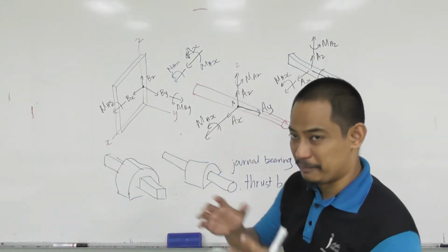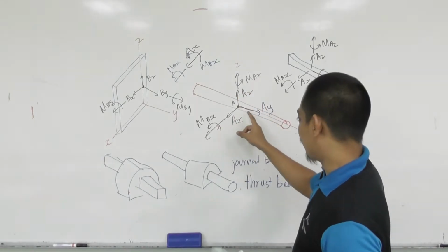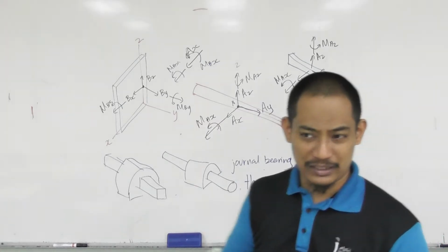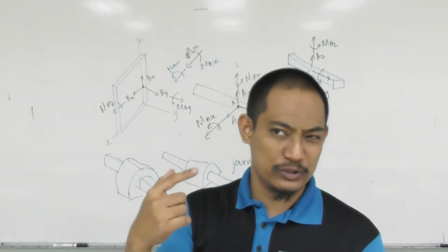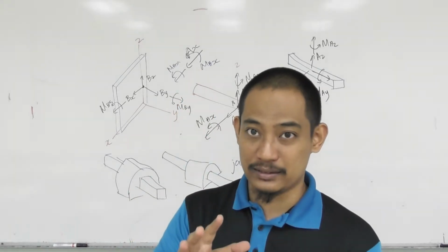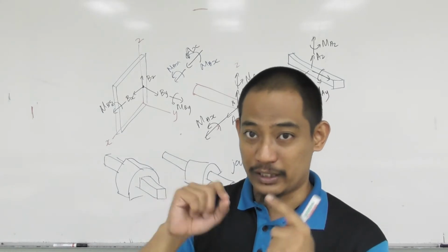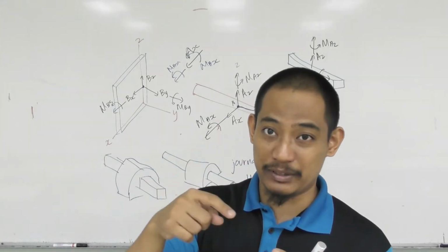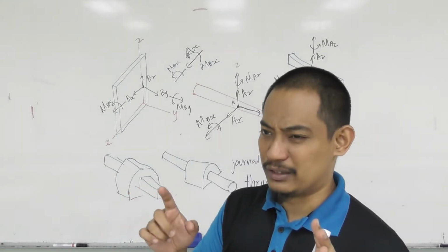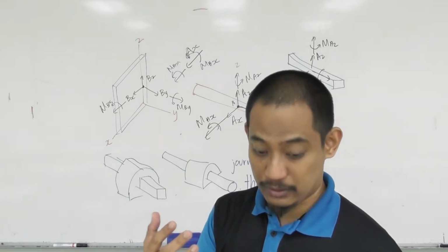If you draw in a mixed way, for AX you draw backward there, for AY positive here, for AZ suddenly downward, then when you get a negative, it's quite confusing. Is it upward or downward, etc.? And you have to check back again, right? So it makes life easy for you to check, in the exam especially, and also for the examiner. Assume everything in the positive direction, so that whenever you get a negative value, you know it's a negative i, negative j or negative k direction, right?